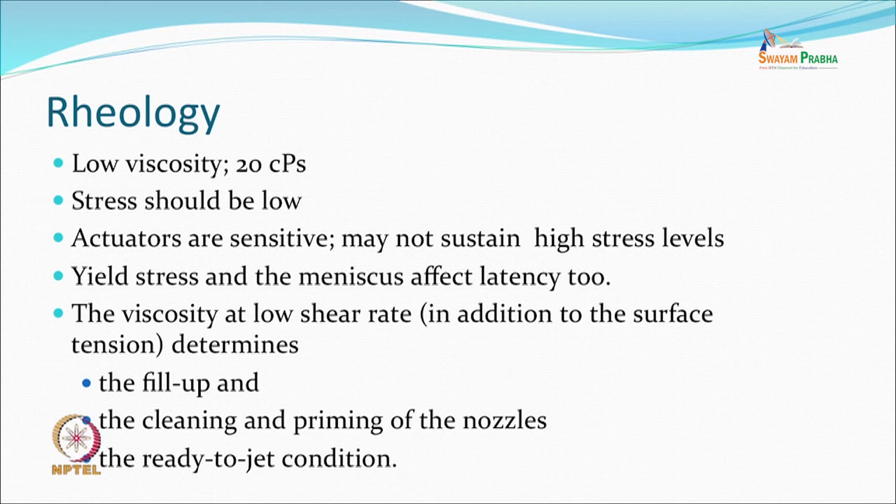There is a station at the end where the print head goes and rests at the end of the machine. This is called priming, and there can be some cleaning also happening, so that the next time when it goes for the printing to the other direction, the jetting is very nice. So, it is always in a ready to jet condition.